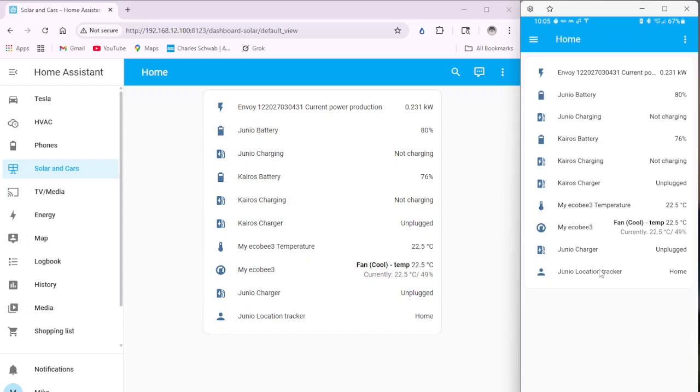What I'm doing is allowing the 2021 to charge early in the day and late in the day, and charge the 2026 only when we have peak solar between 11 a.m. and 4 p.m. So it makes some charging decisions based on the time of day, whether or not the other car is charging, whether I want it to keep charging or start charging because I have a whole lot of solar and the car needs it anyway.